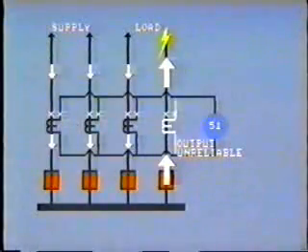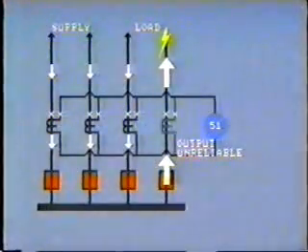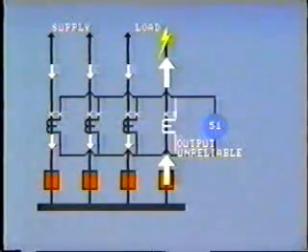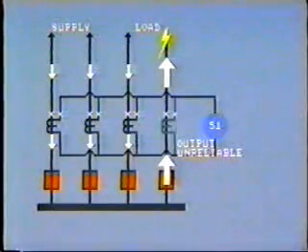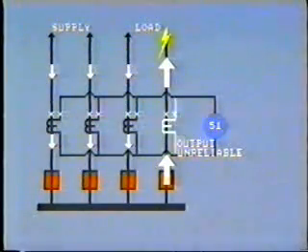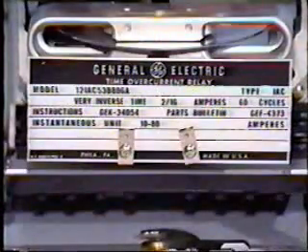So now we have two factors resulting from saturation. A, the non-increase in secondary current as the primary exceeds the saturation point, usually about 20 times rated. And B, the reduction and distortion of secondary current due to the declining DC component of the transient fault current. All this means that for the first few cycles after initiation of the fault, the output of the heavily loaded CT will be most unreliable and will probably cause false tripping. As we shall see, there are several ways to get around this problem.